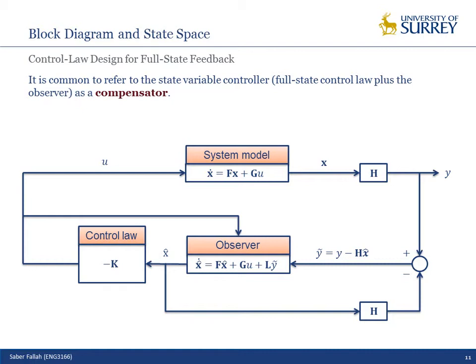The state of the system depends on how you define it. If you look at the references I gave you, most are publications I made. You have different choices for defining the state of the system. But the most appropriate and practical is Zs, the sprung mass displacement, and velocity, and suspension deflection, delta Z, Zs minus Zu, Z dot S minus Z dot U.